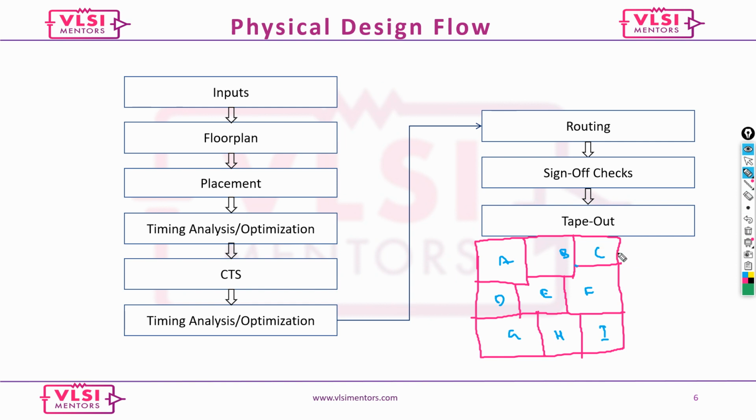But at full chip level, once your block is clean, you have to give the design collaterals back to full chip. Now they run your STA from a full chip angle, and they run PV from a full chip angle. Even if your block is clean, you may have a violation at the interfaces. You may have ports, or shapes coming close to the boundary. So all these interface things also need to be cleaned.